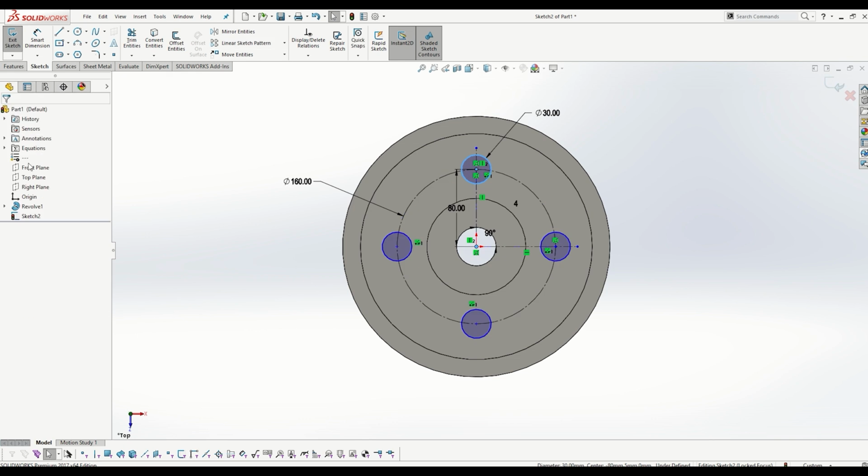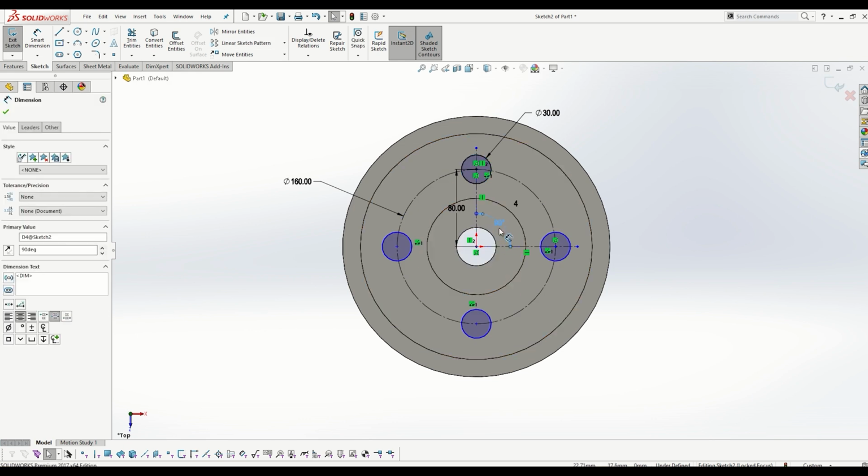Okay, see, I set the dimensioning spacing so each instance has 90-degree spacing, and the number of count will be 4. Suppose I increase or decrease the count, the spacing will be reduced accordingly. So no need to go for the pattern option again.